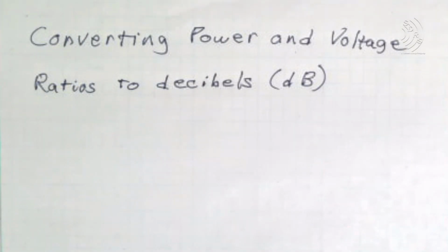Radio frequency and wireless engineers typically use decibels, or dB, to represent power ratios such as the gain of an amplifier or loss introduced by attenuators, cables, filters, or other passive components. We can also express absolute power levels in decibels by representing the ratio of an absolute power to a reference power level, such as 1 milliwatt or 1 watt, in decibel units.